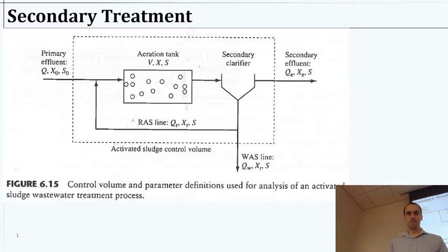All right. So today we're talking about secondary treatment, primary being the screen, bar rack, that kind of stuff, and the first sedimentation basin. That gets out some of the stuff, and that'll typically reduce the BOD by maybe 30 or 40%. It actually does a decent job because you're settling out a lot of solids that would otherwise be a problem, or have a lot of organics associated. But really, the bulk of the work is being done by the aeration basin, activated sludge.